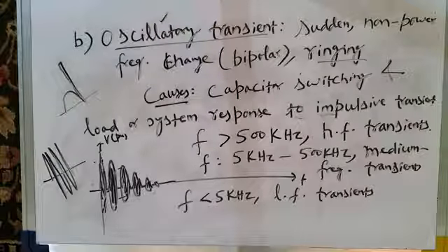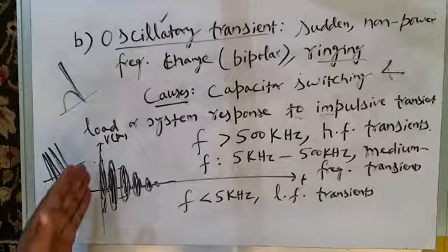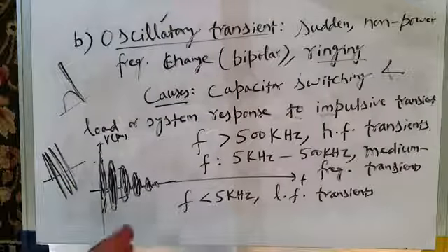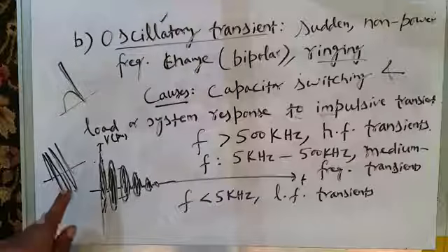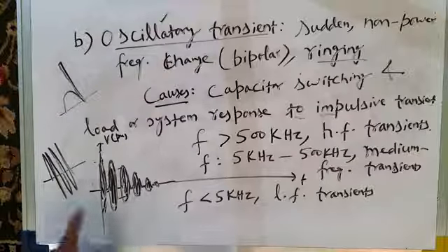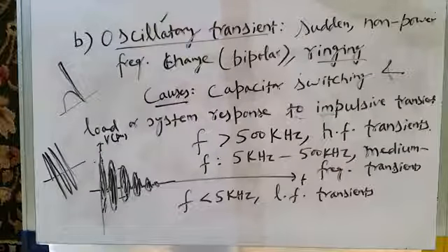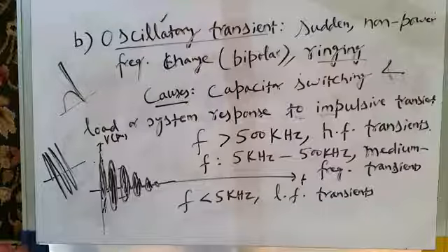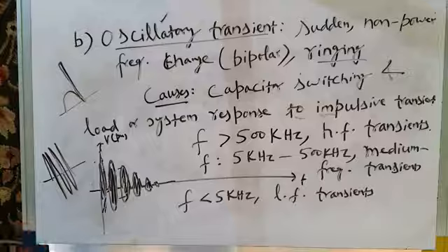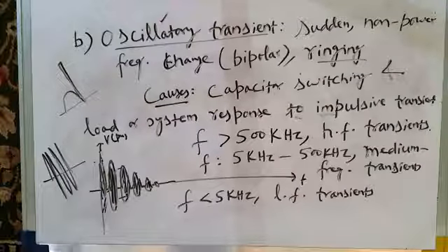So this was about the first type of power quality problem, which comes under the category of events. Now, why does this type of power quality problem, that's transients, whether it is impulsive transient or oscillatory transient, come under the category of events? Because these transients occur only once in a while. Your line or your feeder does not receive a lightning strike every day. Lightning strike may occur only once in a while, maybe once in 6 months, once in a few months.